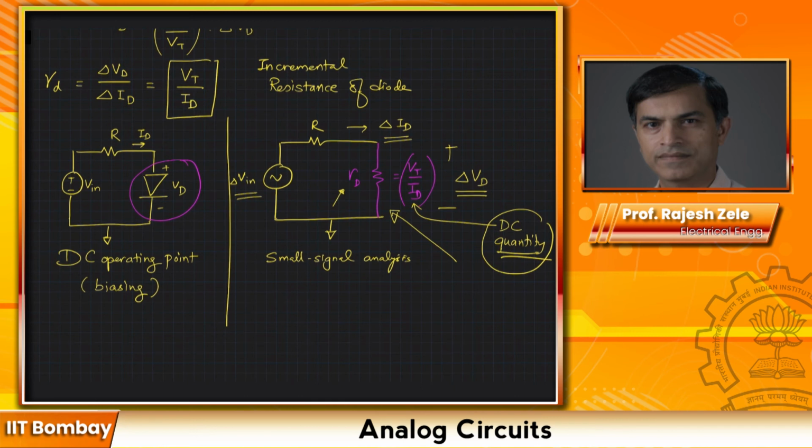When you're doing simulations, the same thing holds true. You will do a DC operating point and you will do AC analysis. The AC analysis part is extremely fast for the simulator because it's a linearized circuit. The complete nonlinear analysis of the circuit is something like a transient analysis, where we are doing KCL, KVL and charge conservation, all those equations at each time point, and that can take a long time.